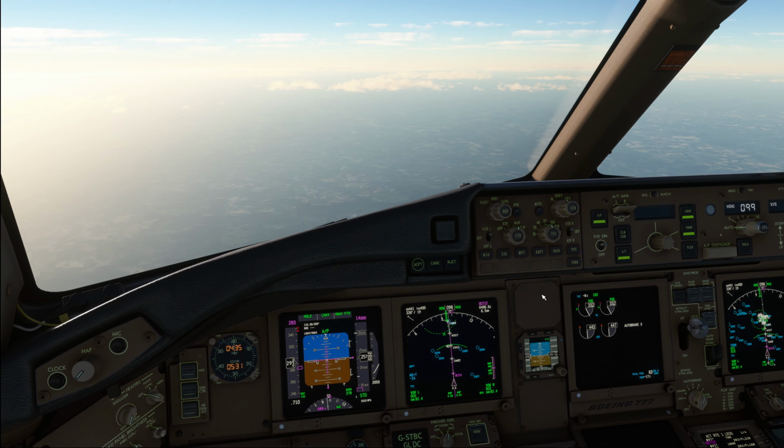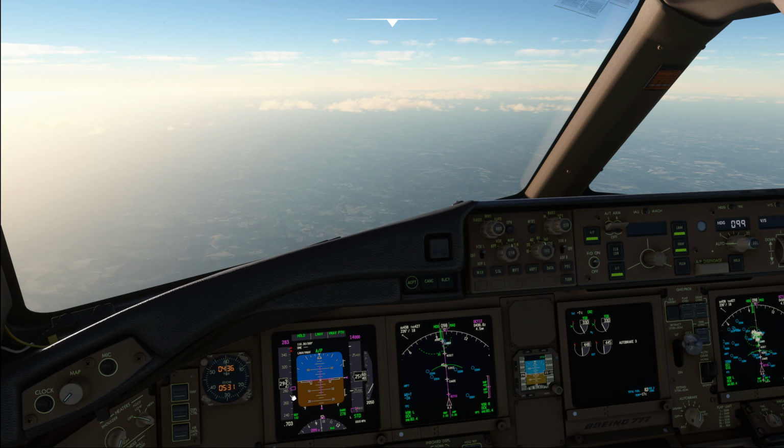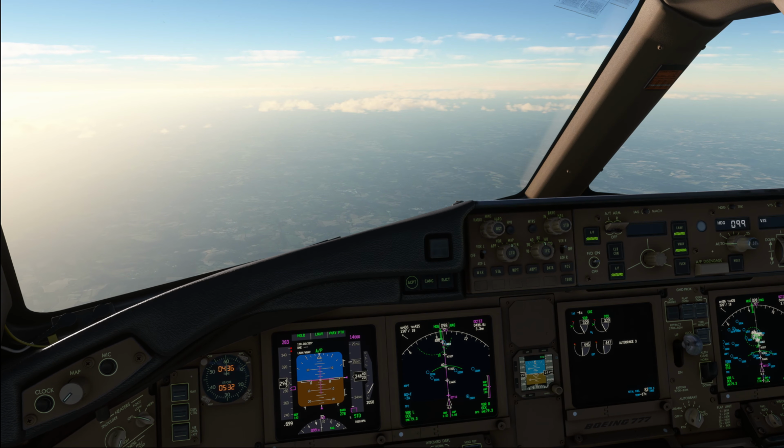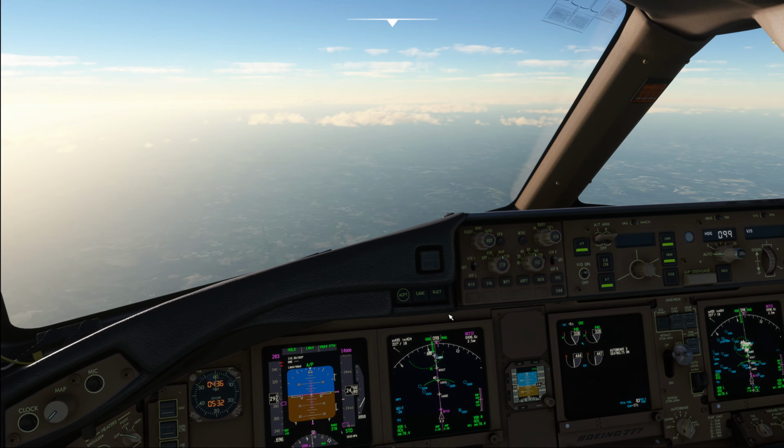Now, the pilot should normally follow the descent path with a couple of mental calculations. We will talk about those in a few moments, but let's first talk about the seatbelt sign. So, different operators use different techniques. One 777 operator normally turns on the fasten seatbelt sign in the descent when passing approximately flight level 250 or the top of descent, depending on whichever is later. That operator flies both short haul and long haul in his 777s. So passing flight level 250, we can turn the seatbelt sign on.